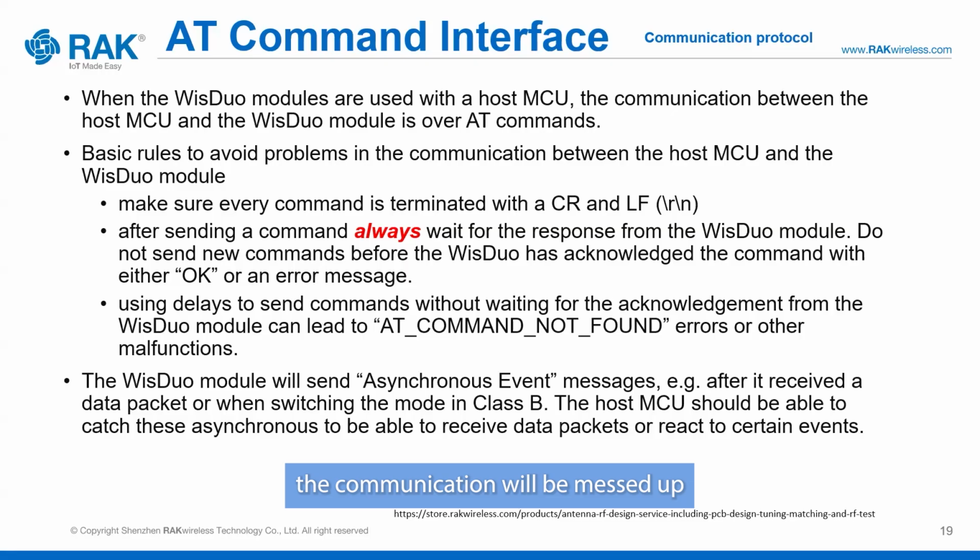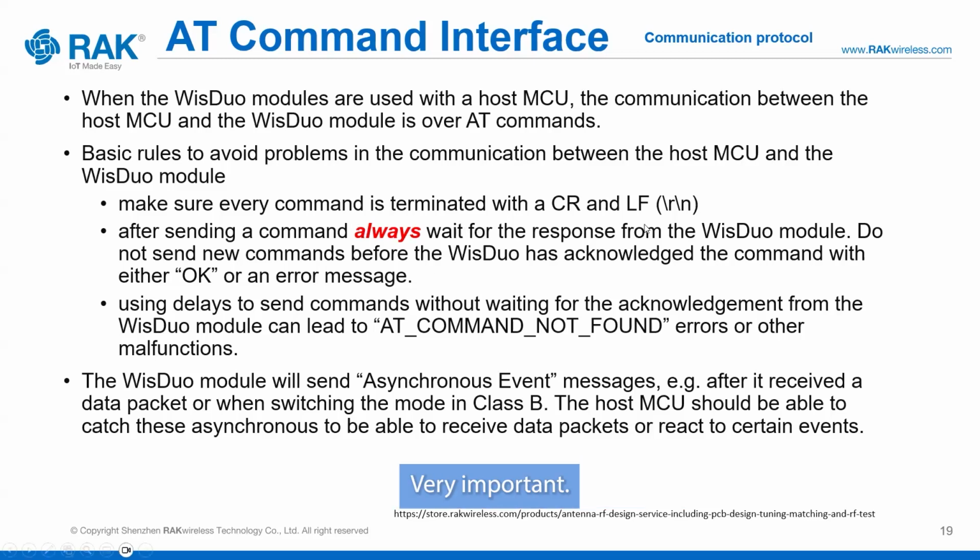Otherwise, the communication will be messed up and can lead to AT command not found or other malfunctions, AT commands misinterpreted. So it's very important to always wait for the response.